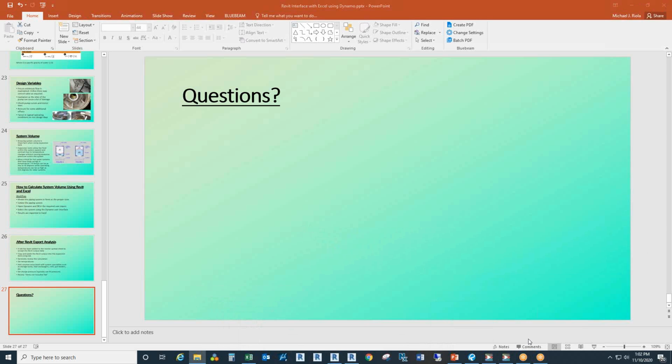So even if you have a certain return duct going from a rooftop unit in one area through to another, even if you're doing the duct static pressure drop, consider the return path from all the spaces back to at least your point of return. That's a great point. Yeah, that burned me one time.